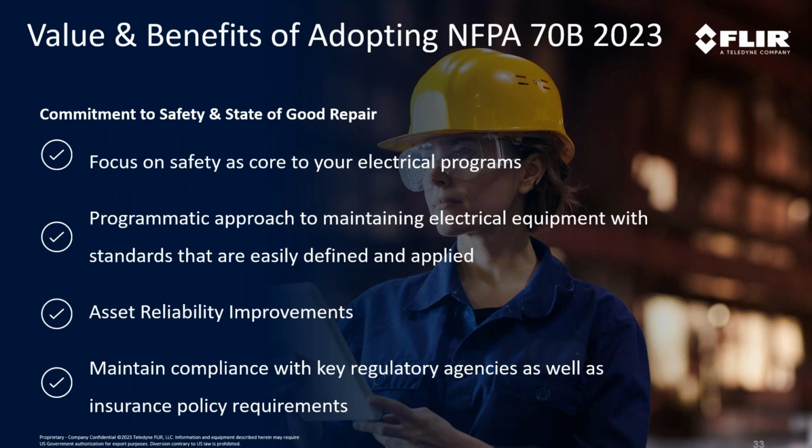So I kind of hit on this at the beginning: we're doing this because we need to. It's a good idea to, but as we move towards next year, there are going to be more regulatory agencies such as OSHA that are out there. They're going to be looking to this to ensure that you are complying with this standard. So if, heaven forbid, there were an incident, they're going to look at your maintenance records. They're going to understand whether or not you were performing those thermal inspections or electrical inspections with the correct frequencies, and they're going to want to make sure that you are doing so based on the NFPA standards that are there.